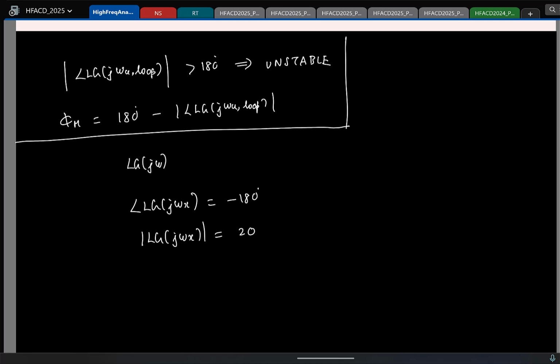Okay, which means you have to relook at the understanding once again. See, what is this check we have to do to see if the system is stable or not? Phase margin. Or we just look at the phase at the unity loop gain frequency, right? That has to be less than 180 degrees. So what is the information given to me right now? Maybe if I sketch it again, let us say this is the magnitude here, and here I sketch the phase.